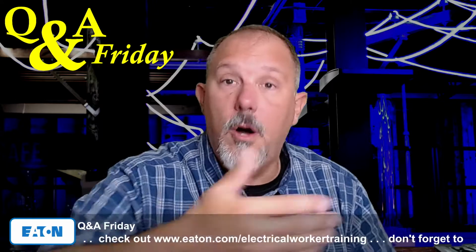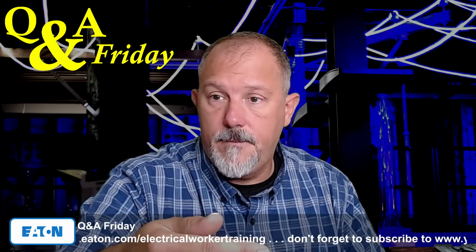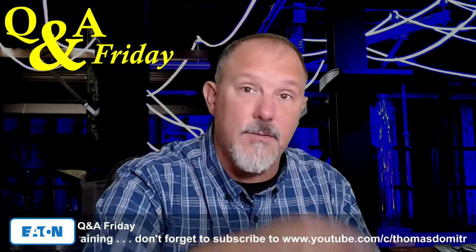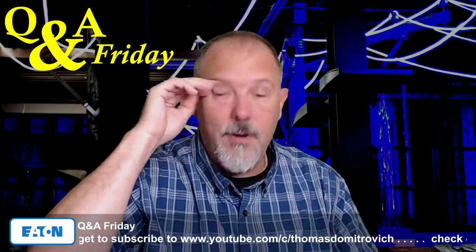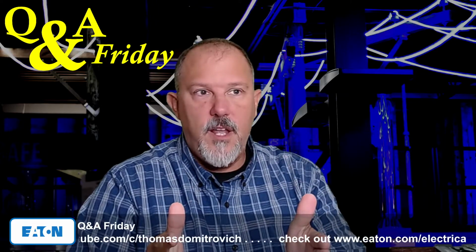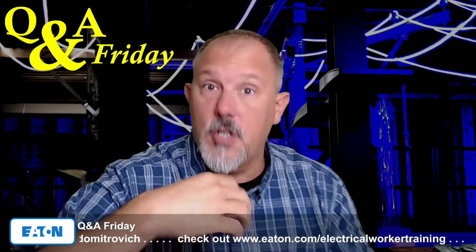But if you hardwire that appliance to an outlet that doesn't have a GFCI receptacle, then it still needs to be provided GFCI protection for that outlet. So I think you're covered both ways. That's the language for the outlet: if you put a GFCI receptacle in there, you're providing GFCI protection for the outlet because you've turned it into a receptacle outlet with GFCI.